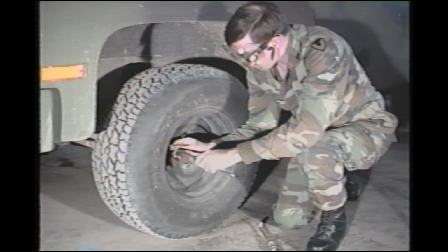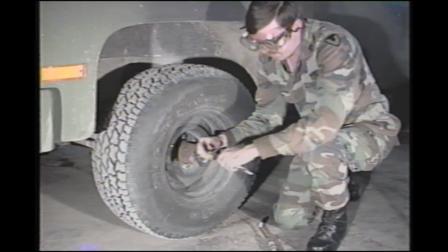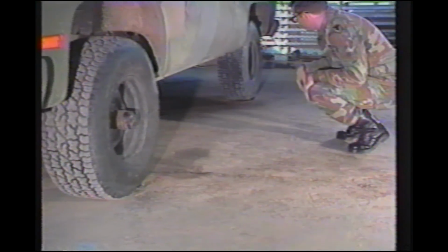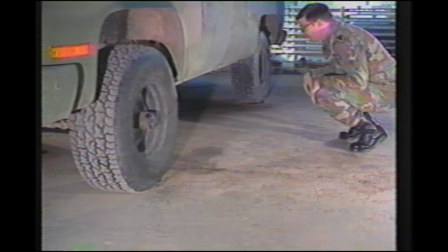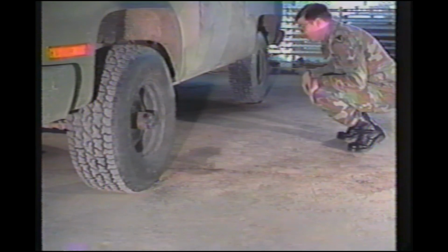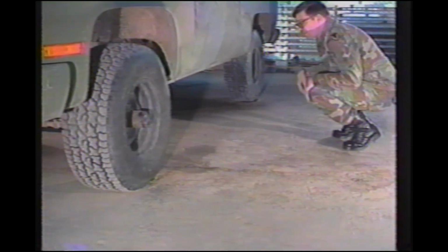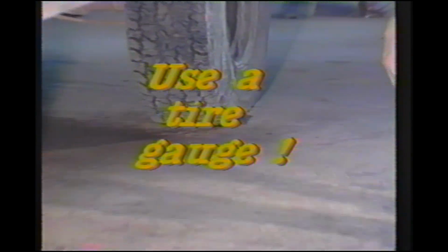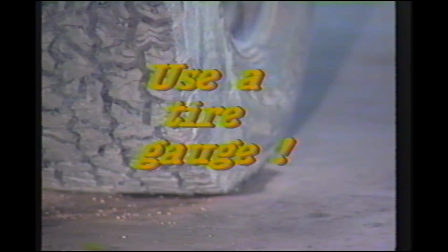Use caution when inflating the tire. Accidental overinflation will stretch the tire and tear the cords. Remember, tire pressure cannot be judged by how flat the tire appears. Looks can be deceiving. The only way to check the pressure is with a tire gauge. Improper tire inflation creates heat and will lead to catastrophic tire failure.